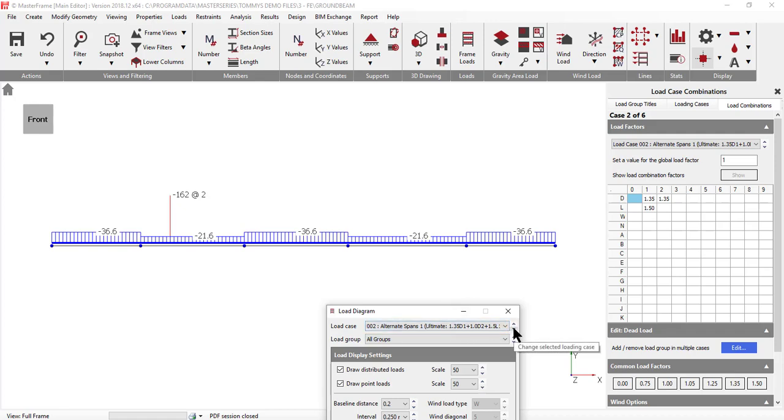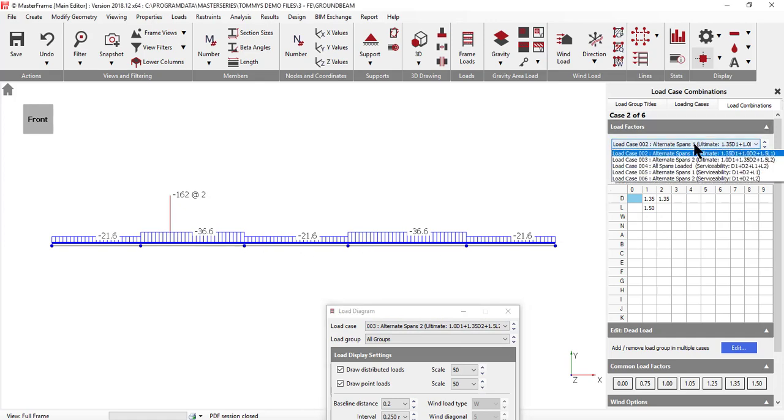If I went to the third case here, I would say it's minimum, maximum, minimum, and I just do that by simply alternating this again to be maximum on span 2 and span 4, the even spans. So very simply we're able to do this patterning of the loads.